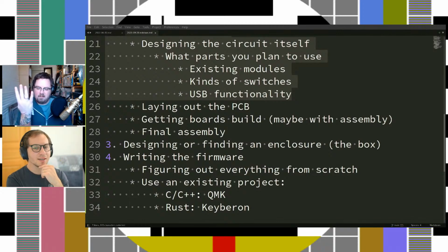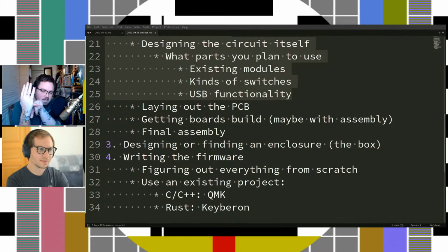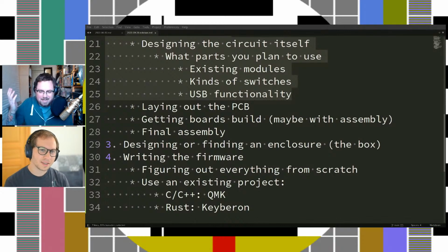Or a lot of them will have ones where they have 4 on the top and 1 on the end. So you might be able to put the 4 on the top pointing outwards, and then the one on the end, you just have a tiny little 5 centimeter USB cable that plugs into a very simple microcontroller. So then you have a very smart, off the shelf, verified to actually work USB hub. And sometimes that's a nice way to cheat if you're only making one. You wouldn't want to make an assembly line of that, but for one, find one that fits your size and then just design your plastic or wooden housing so that it's got mounting points where there should be.